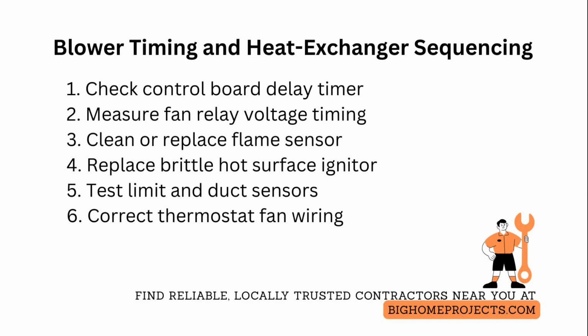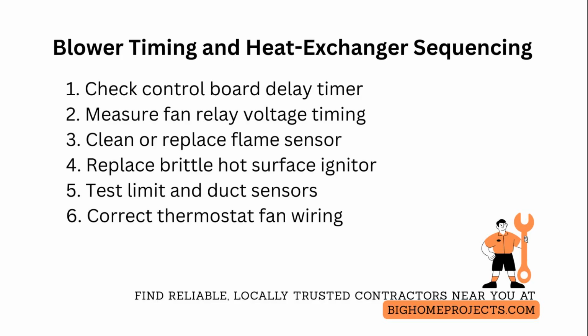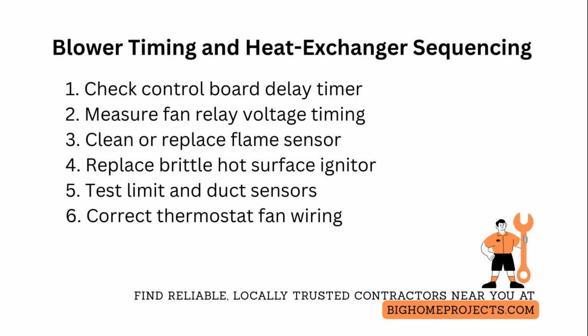Audit the blower relay and motor start capacitor. A sticking relay or a marginal capacitor can make the motor come on at odd times. Bench test the capacitor for microfarad drift and replace it if it is beyond 10% of rated value.